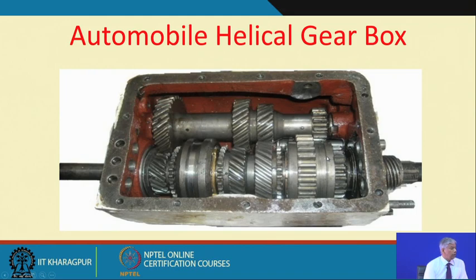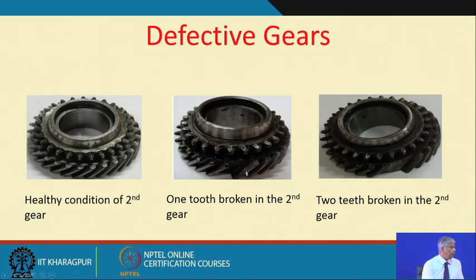So, and then you can have a first gear, second gear, third gear, fourth gear and so on, or a reversing gear. And then of course, this is a spur gear and this is a helical gear and so on. So, helical gears make a nice smooth contact as opposed to spur gears, and no matter what, these gears are having a gearbox, there is a lot of lubricant to take the heat away, and